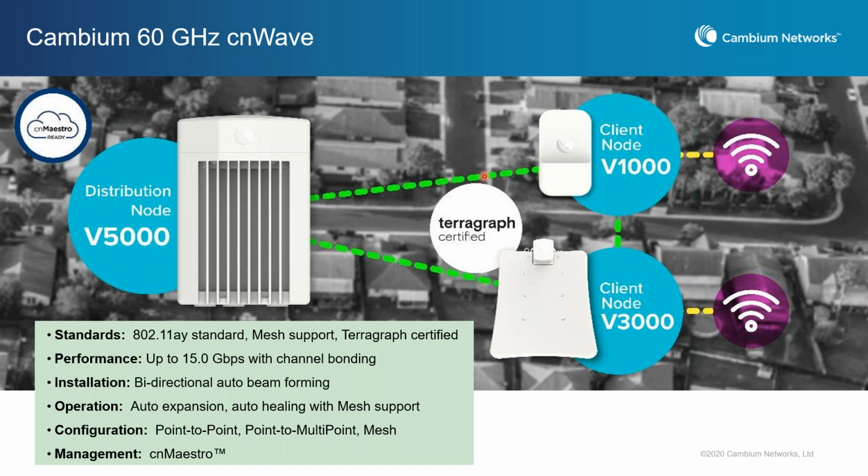Yes, ultimately the configuration is pushed down using cnMaestro, but we also provide an onboard end-to-end controller, or onboard cnMaestro. So if you're running a small network, let's say a point-to-point, or a small scale point-to-multipoint with fewer than 21 nodes, you could enable the onboard end-to-end controller. Then everything will be pushed down from